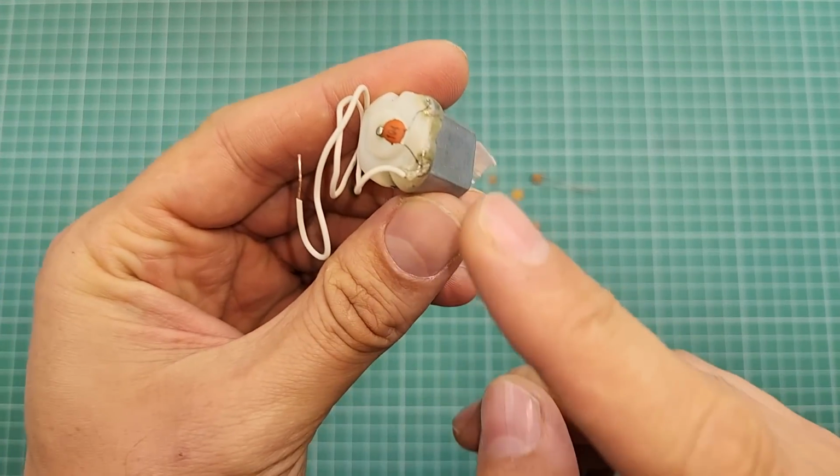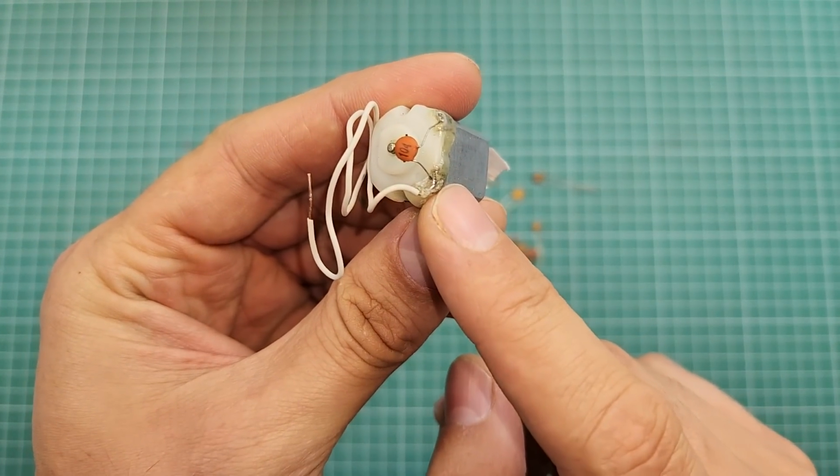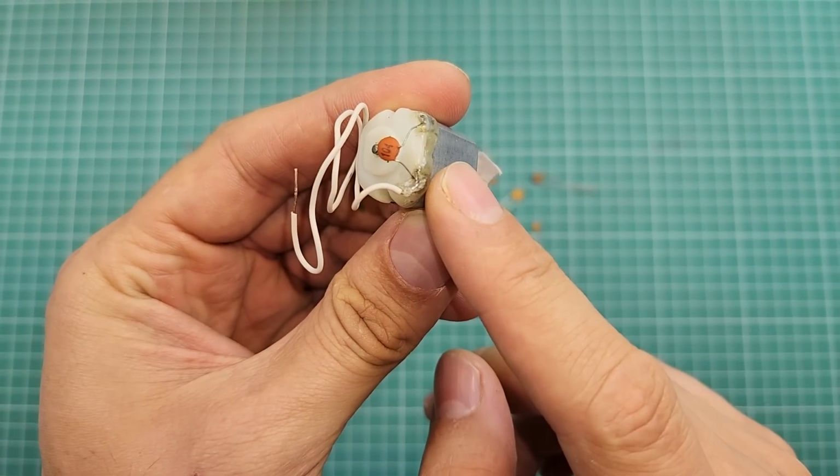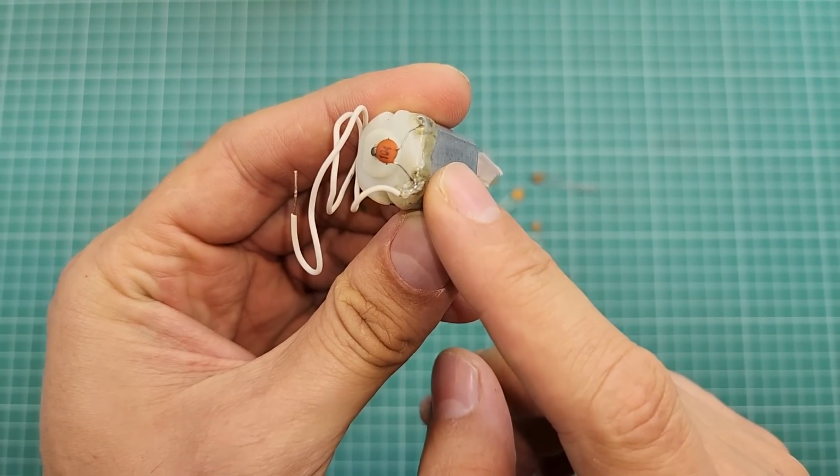Another example is these capacitors at the DC motor leads. They are used for eliminating noises and spikes generated by the motor. You may ask, why are ceramic capacitors used there? This is a good question, but the answer is simple. Keep this golden rule in your mind. You have to determine the required capacitance value, then consider the voltage rating, and you are done. In most cases, any type of capacitor will work.